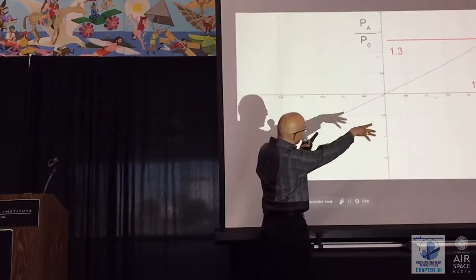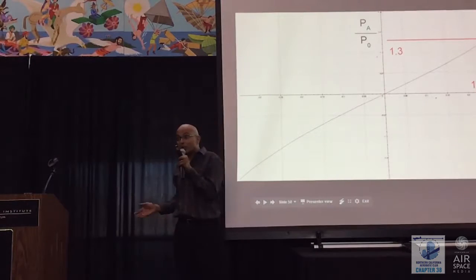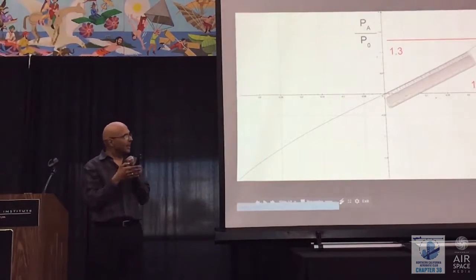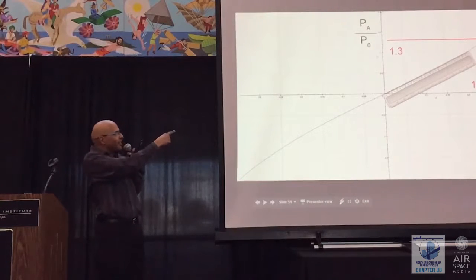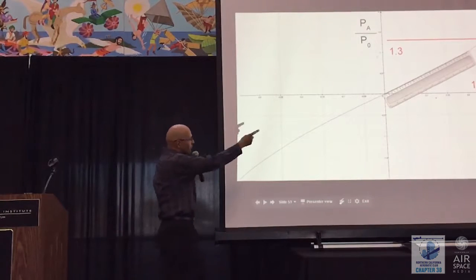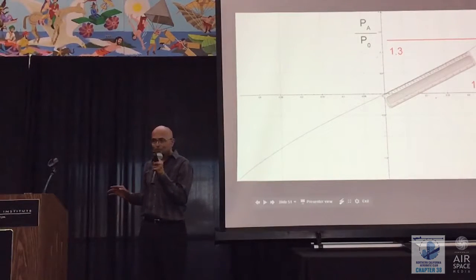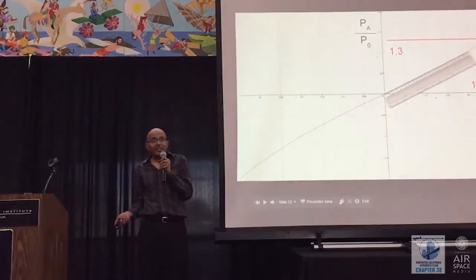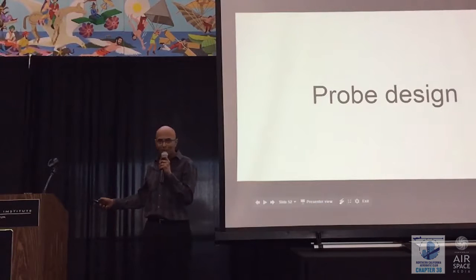And at about 15 degrees angle of attack, we get a ratio of about 1.3. So it's actually a very good solid signal. And in fact, you could do worse than just draw this as a straight line. Now, obviously, we're going to have the actual curve in there, but it's really a very simple correlation. So that is basically the theory behind our air data probe, and we'll show you more of it as we go along. In fact, I'm going to talk about it right now.